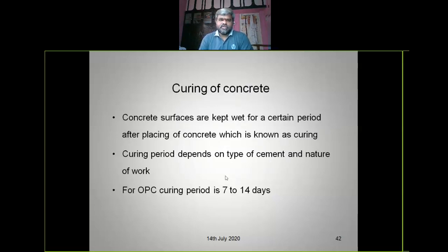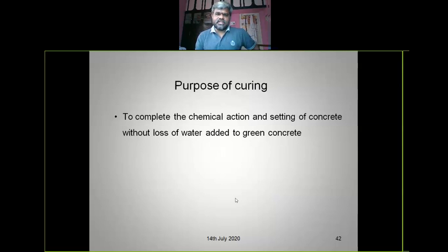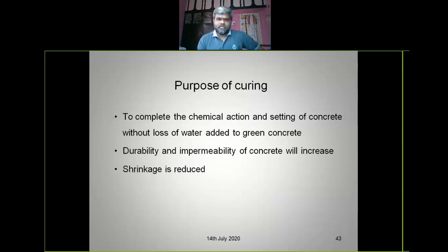Curing next. Keeping concrete surfaces wet for a certain period after placing of concrete is known as curing. Curing period depends on the type of the cement and nature of work. For OPC, the curing period is 7 to 14 days. Right. The purpose of curing is to complete the chemical action and setting of concrete without losing the water added to green concrete. Durability and impermeability of concrete will be increased.